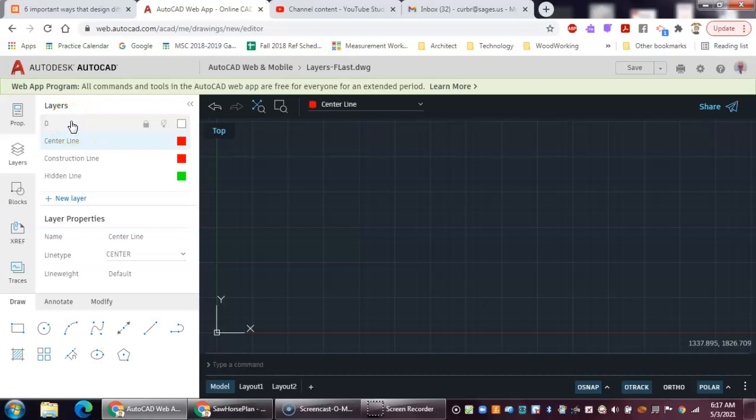So I'm going to click on my layers property, object layer, and we're going to draw a line. Now I'm going to insert that line at 5,5. That's going to be my endpoint. If you look right now down into your lower right-hand corner of the drawing area, notice down here where our X and Y coordinate is, 4,044.799 minus 130.495. So we're zoomed way out.